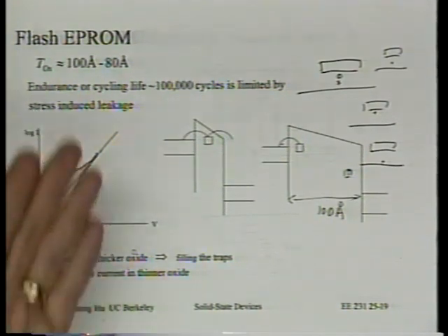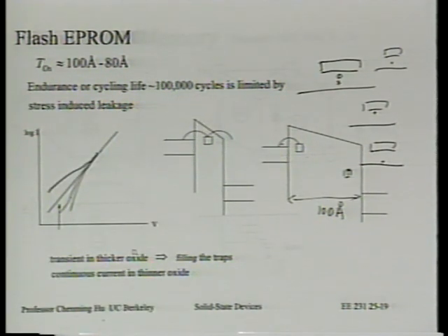When this 100 angstrom oxide was first used for the non-volatile memories, it was considered really daring, because do you know what the logic transistor gate oxide was at that time? It's probably something like 500 angstrom. Now, the logic transistor uses 20 angstrom. And guess how thick the non-volatile memory's gate oxide stays at? It stays at 100 angstrom. So this is not very good for scaling.